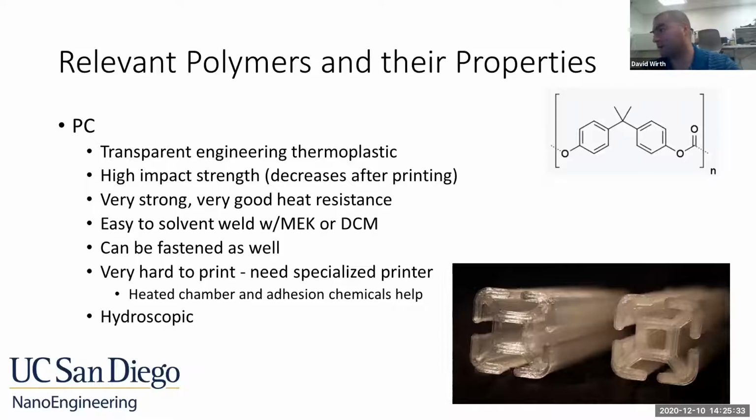So then we kind of go up the scale again to polycarbonate. A lot of people will start out and try to print polycarbonate because they're like, oh, polycarbonate, this is the best. Let's print something out of polycarbonate. The problem here is printed parts out of polycarbonate are not nearly as strong as cast or machined parts out of polycarbonate. And I'll talk about that a little bit later.